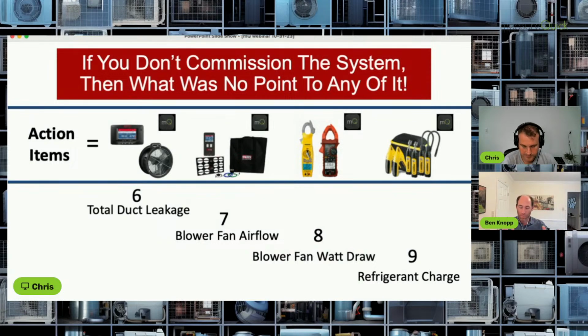So, I think there's a lot of misunderstanding about ERVs. I hear a lot of, oh, should we do an ERV or a dehumidifier? Like they're the same. Now, ERVs can remove a significant amount of water in the summer, but they are not dehumidifiers. An ERV in the summer adds water to the space. It just adds less water than straight outdoor air.